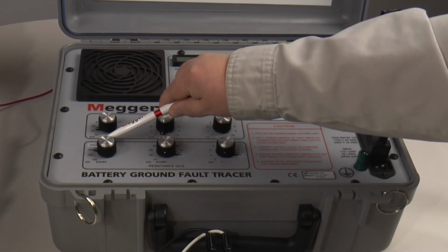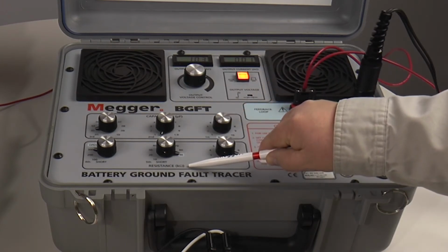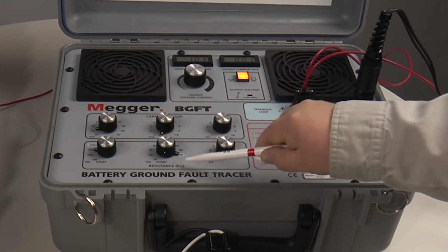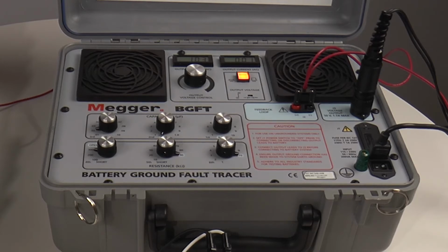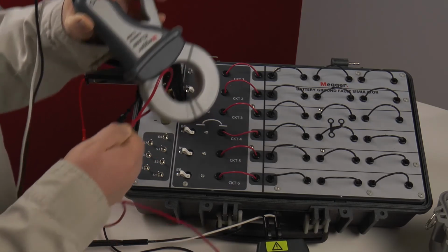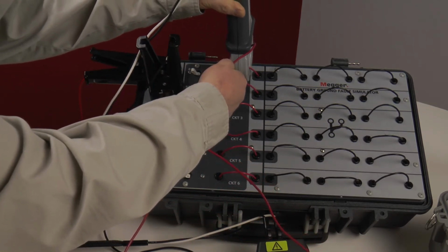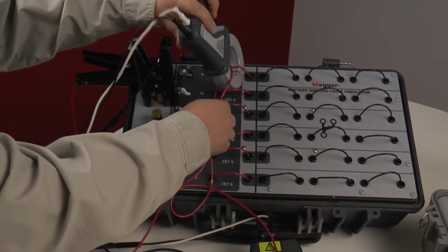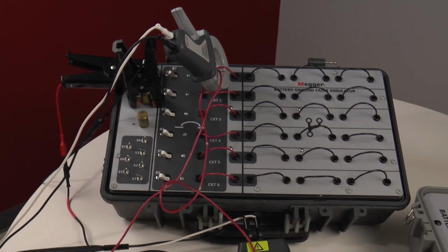This circuit is purely capacitive and just drawing leakage current. This is what we call a phantom fault. It is due to long cable runs. If we were to trace this circuit, we would trace all day and never find a fault. We now go to the breaker with the next highest level of fault current and characterize that breaker. In this case, that is circuit 1.